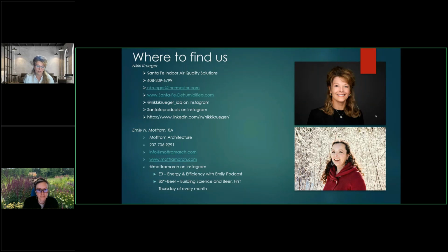And the second part: there is a video that I have attached, called The Dripping Point, that you should be getting a link to, that I did a couple years ago. It talks about dehumidifiers and installing them correctly, always making sure that the supply of that dehumidifier is on the supply side of the HVAC system and not going into the return side. The reason is you're not going to get the dehumidification from your AC system if you put it on that return side, because we generate heat with a dehumidifier.